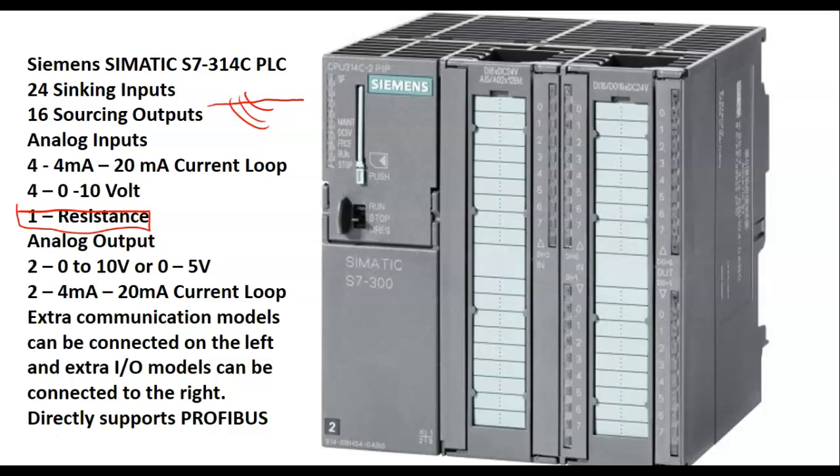Electromagnetic interference cannot generate a current. It can change a voltage, but it can't change a current. So one of the most popular in industry is what we call a 4 to 20 milliamp current loop, which means if you're outputting an off, there's never a true off. An off would be equal to 4 milliamps of current flow, and a true or an on would be equal to 20 milliamps. So we can run these over great distances.